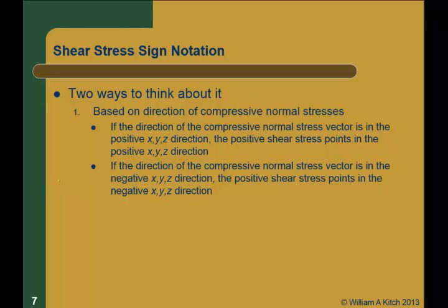Maybe the better way to write it is that if it's a positive plane, like we just defined positive and negative planes, positive shear stresses act in the positive axis direction. If it's a negative plane, positive shear stresses act in a negative direction. So, these definitions, although very wordy, are correct.